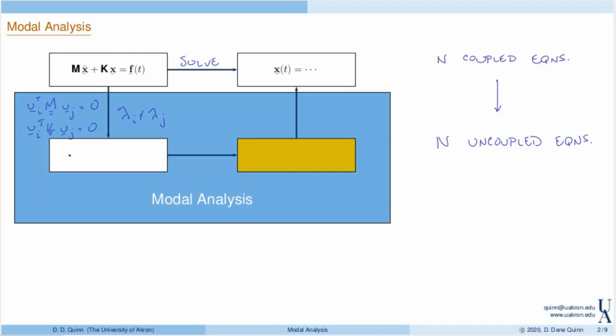And this allows us to ultimately write a set of equations that look like q double dot plus lambda times q equals some forcing function. And all of this remains to be determined in this lecture. But essentially these are modal coordinates. Lambda here is the eigenvalue. And notice that this equation essentially amounts to a single degree of freedom undamped forced equation. Again, we have no damping here in the original system.